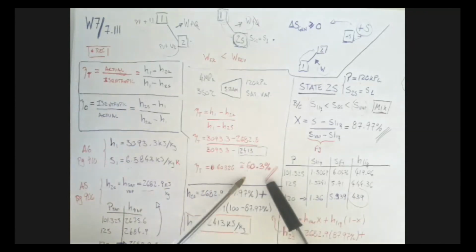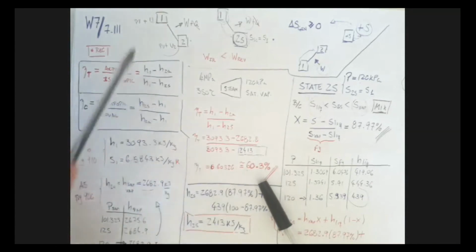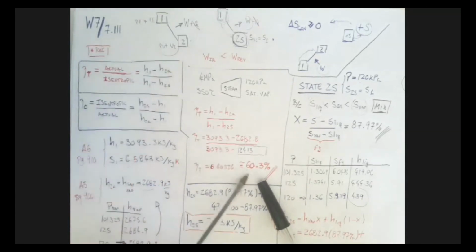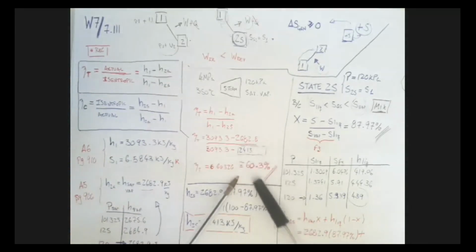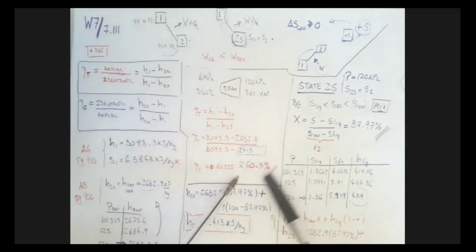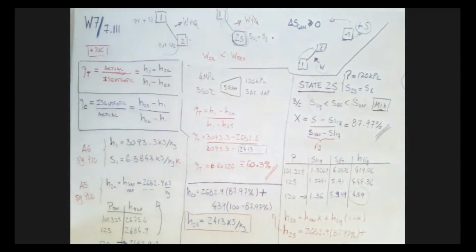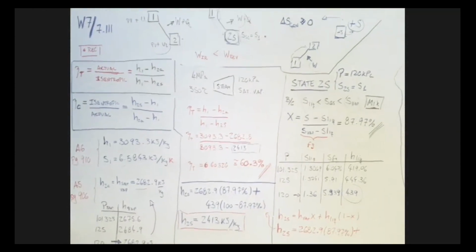And this is very important for you guys as engineers because this is where you have leg room to work, right? This is where you can improve your process. Because you can't create more energy from nothing, that's impossible, but you can definitely make a process that is closer to your isentropic process, so you can make this guy more efficient and therefore have a better process. That's the whole idea around looking for the second law efficiencies and isentropic efficiencies.